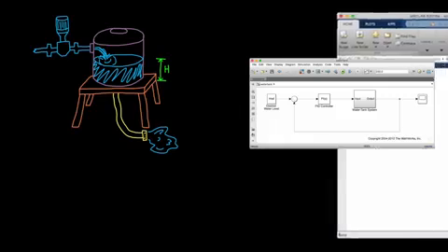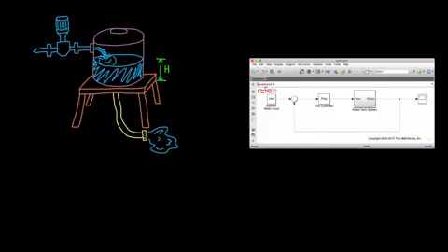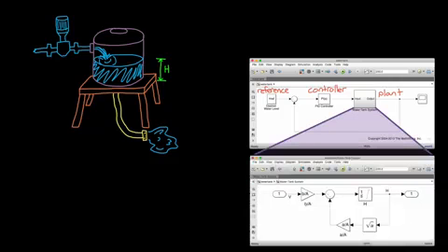And this is a classic feedback system. There's a reference water height, a controller, and a plant that represents the dynamics of the water tank system. The input is voltage and the output is water height. Within the plant subsystem, we have the details on how it's modeled. And from this, we can write out a differential equation for the system. The parameters a, b, and capital A are specific parameters of the tank, and they represent constants related to the flow rate into and out of the tank and the cross-sectional area.